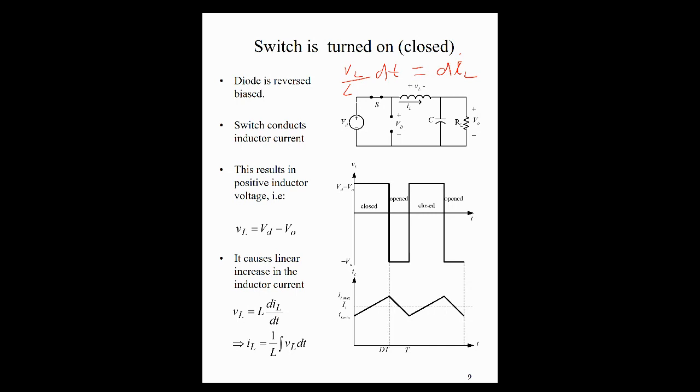So you integrate both sides of this expression with respect to t, and that's how we have I equal to 1 over L times the integral of the voltage across our inductor. We can see clearly that the current during this time when the switch is closed is increasing, because there's a proportional relationship between current and time. That is why we have the current increasing in this region.